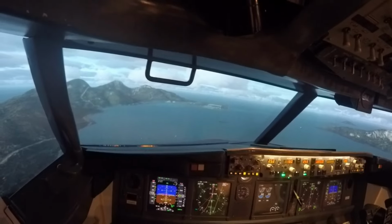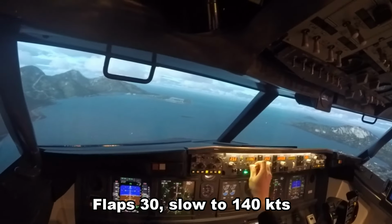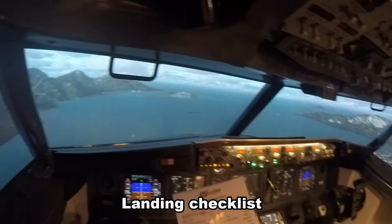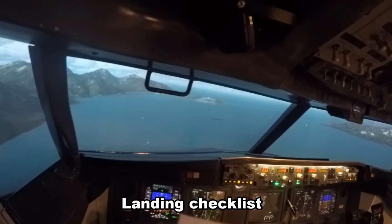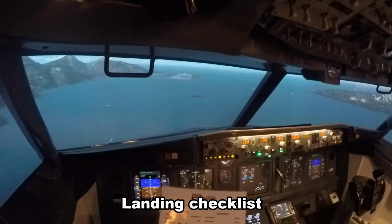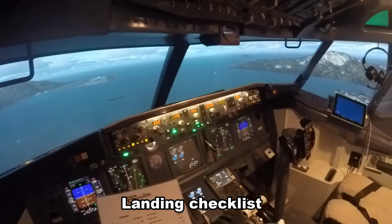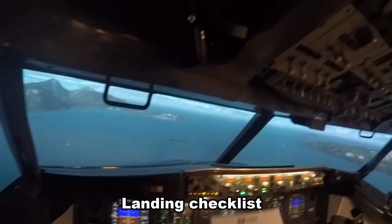And we'll soon drop our flaps to flaps 30, go to speed of 140, and we'll do our landing checklist. So landing checklist, engine start switch is continuous, speed brake is armed, landing gear down 3 green, flaps 30, green light. Landing checklist is complete.